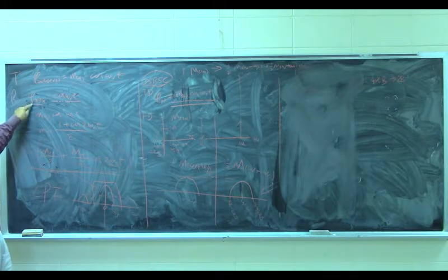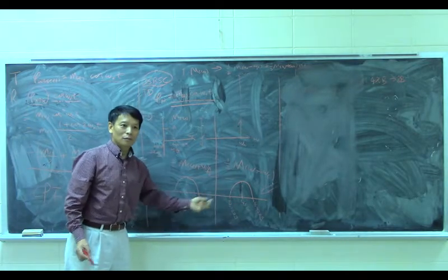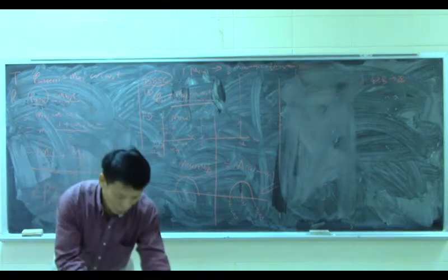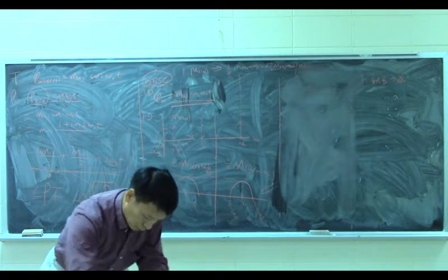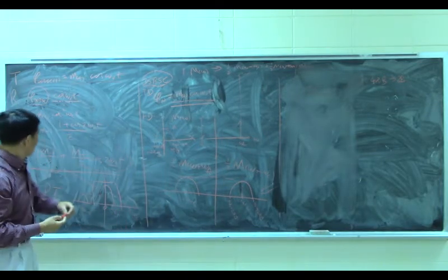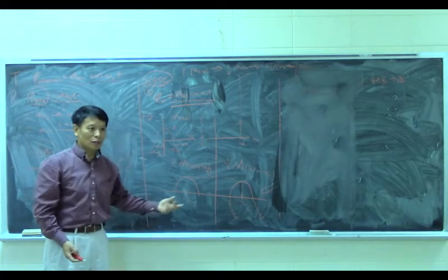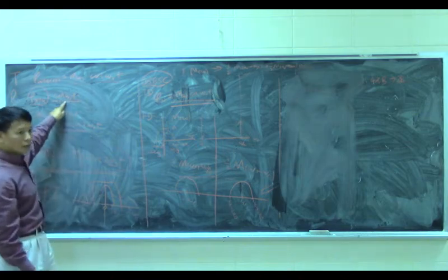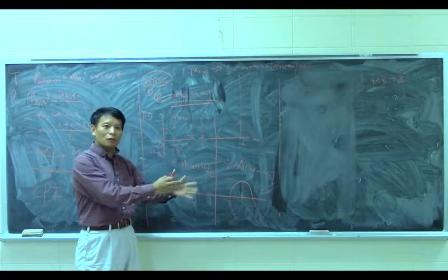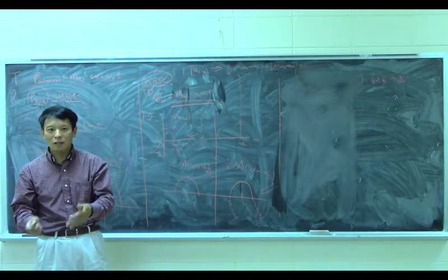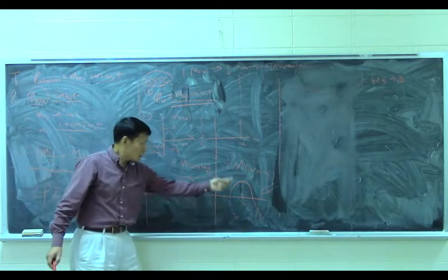Okay, now look at this. What is the spectrum of this? It looks like this. Make sense? That is what we already know. So the double sideband suppressed carrier spectrum looks like this. So that is at the receiver. You multiply by this cosine, that means we shift this spectrum to higher frequencies, centered at omega_c and negative omega_c. What is the center of this spectrum?